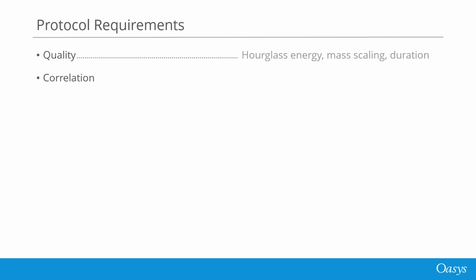Correlation. The main method of validation is an objective comparison of time history signals from various sensors placed on the ATDs and vehicle structures in the physical test and their corresponding entities in the LS-DYNA model. For both the Euro NCAP and C-NCAP protocols, this assessment of correlation must be completed according to ISO TS 18571:2024.